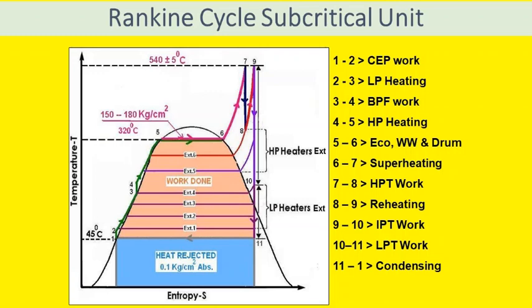There is slight change in temperature of the feed water due to this work, and discharge of the boiler feed pump, that feed water is passed through HP heaters, high pressure heaters. 4 to 5 represent high pressure heating arrangement as a part of regenerative feed water heating, where bleed steam is taken from HP turbine and MP turbine.